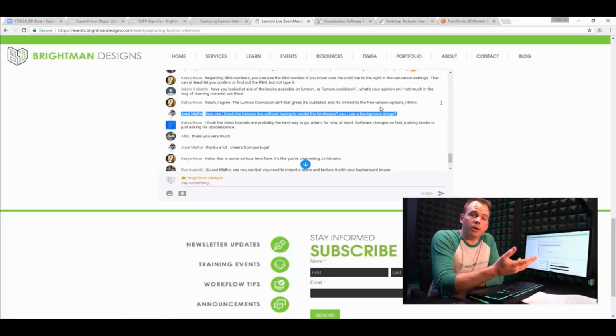Also, there's a really cool new plugin Daniel Tall put out, Placemaker, so you can grab all those buildings and put them in that way too, if you need a little more control over modeling the buildings. There are a lot of options for modeling the site that I'd be more into rather than that old method of a billboard texture. But if you need it quick and easy, you could totally do a billboard texture, save it as a PNG, and it'll show through. So that's one way to do it.